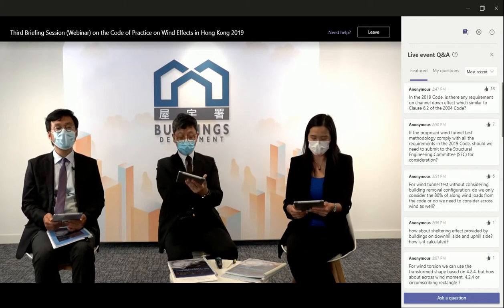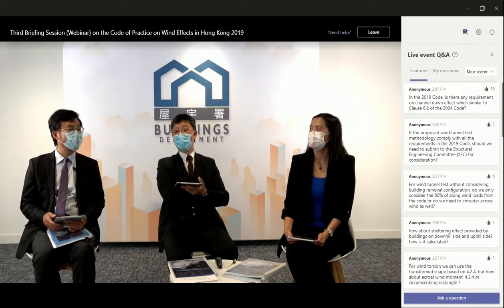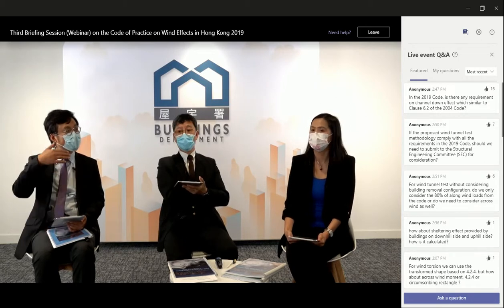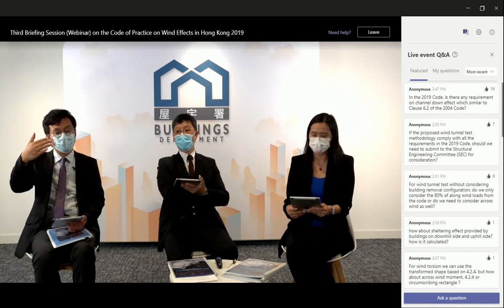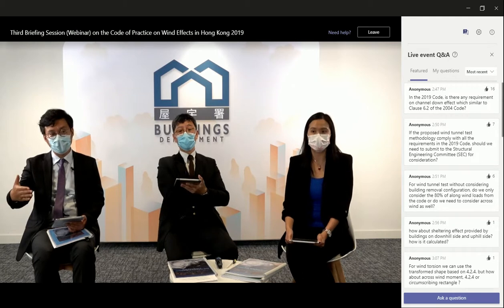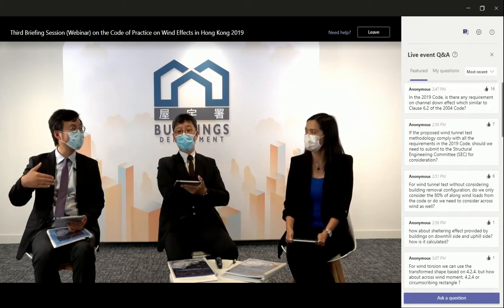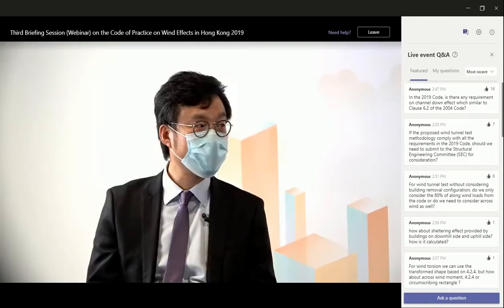Okay, so I think the so-called washdown effect is that when the wind flow hits the building surface, there is a wash down at the lower portion of the building surface. So the wind pressure will be higher than the approaching wind profile. I think that is why some of the audience asked this question. So the answer is also clear, it is yes.